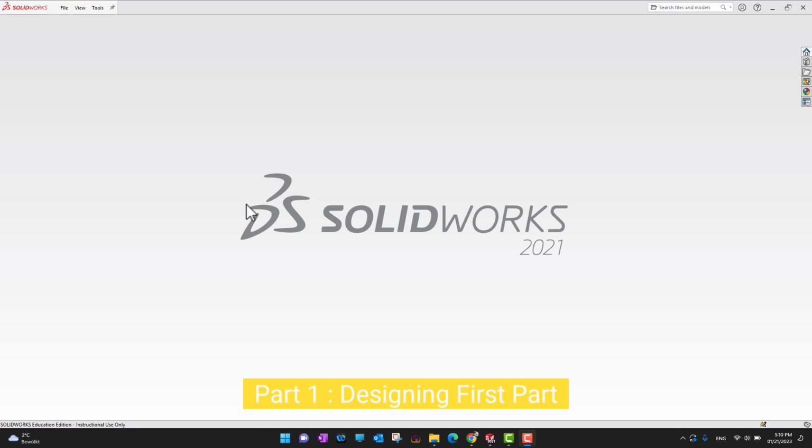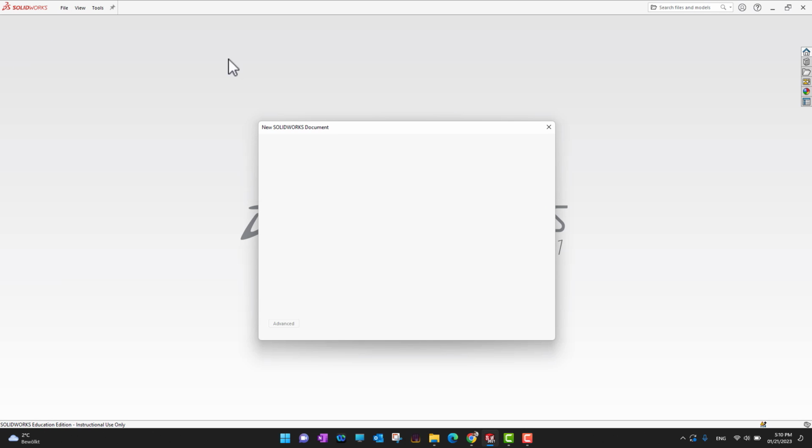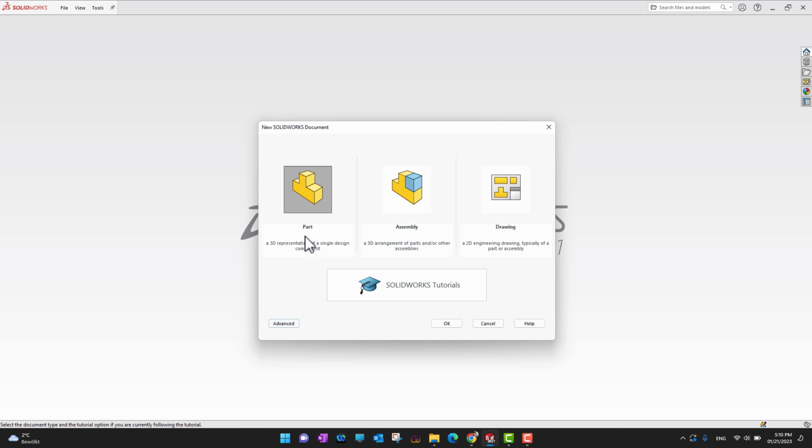I'm going to go into SolidWorks and let's start with a new SolidWorks part. If you want to start, you can click on New, and here, if you want to start with a part, assembly or drawing, you can just select. As in this video we are going to design our first part, I'm going to select Part and then press OK.